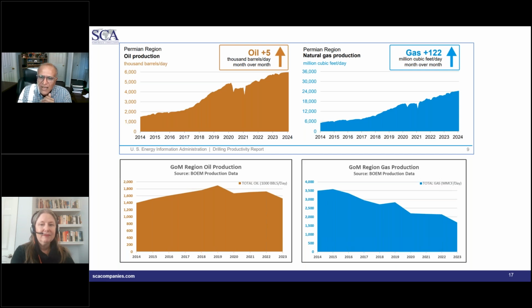You're so right that gas lift can help with some of the quantity of this gas. However, we have to keep in mind that it's basically recirculating gas, meaning your offtake for the gas lift will not be as high. And one of the reasons why gas lift has taken off in the Permian is primarily for that, because we have so much gas and not sufficient pipeline capacity to take it away.